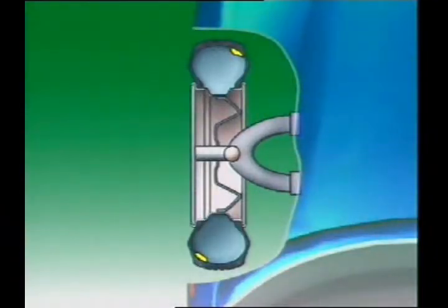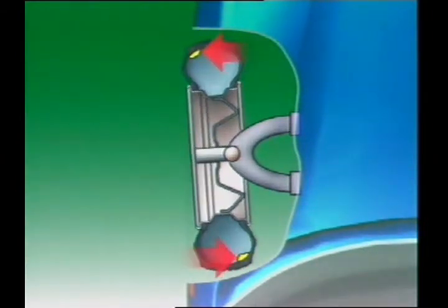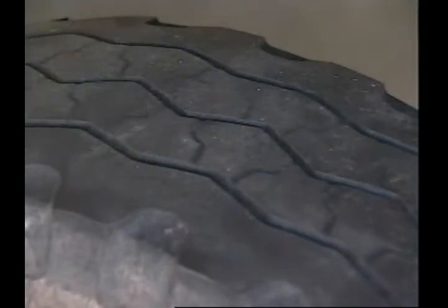Dynamic unbalance causes the wheel assembly to turn inwards and then outwards with each half revolution. As speed rises, rapid side movement of the front wheels causes a sideways vibration or wheel wobble effect at the front of the vehicle. These conditions must be corrected to prevent cupping or dishing of the tread and reduced tread life.